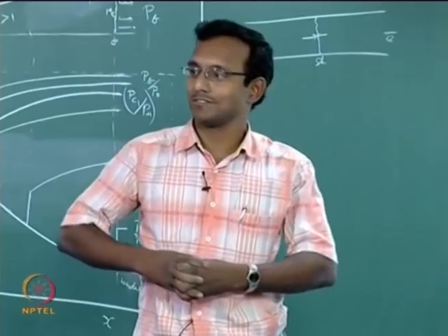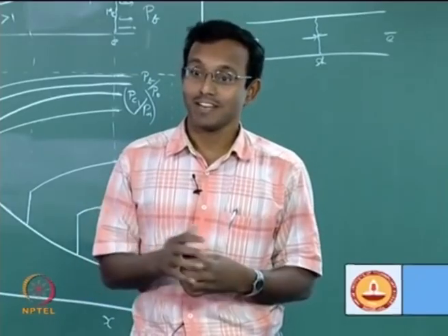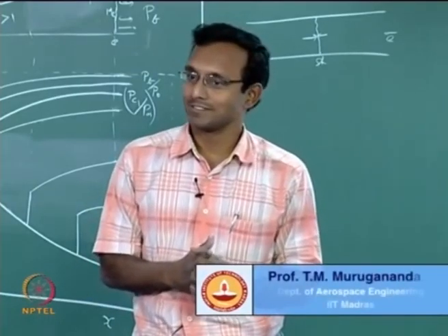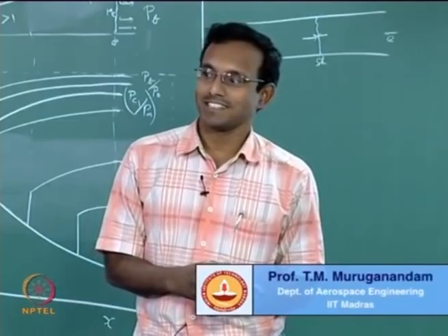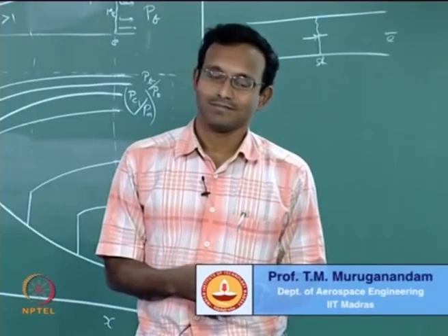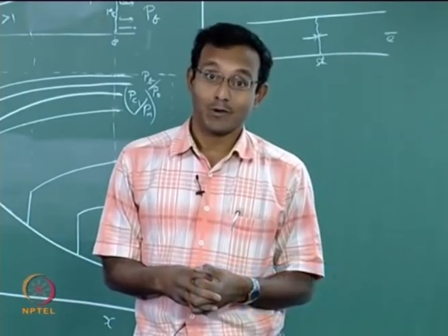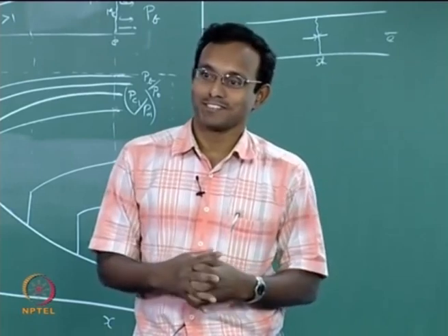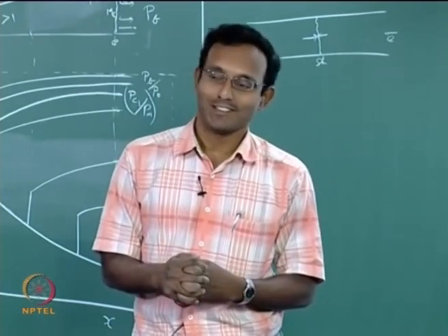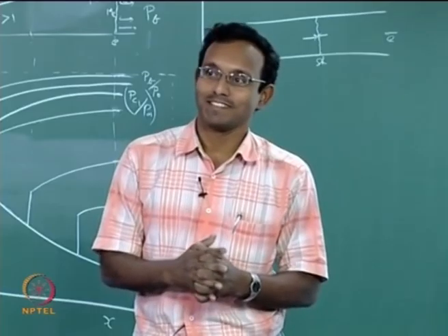Back pressure is continuously decreasing, which means the strength of my shock should increase, right? That is what we have been discussing till now. In fact, the Mach number at the shock is higher. We are seeing that the delta P is lesser, and I know for sure there is nothing wrong in my calculations. Is that logical? Can we explain this? Is the basic question.